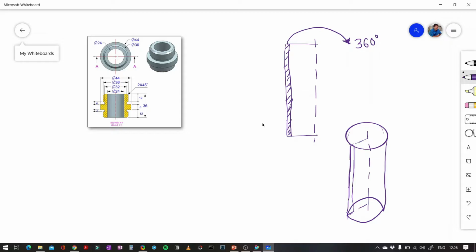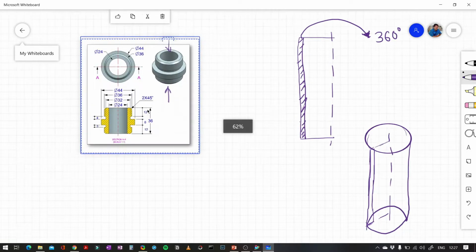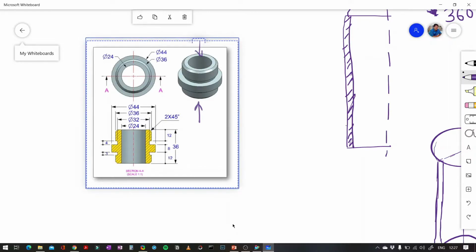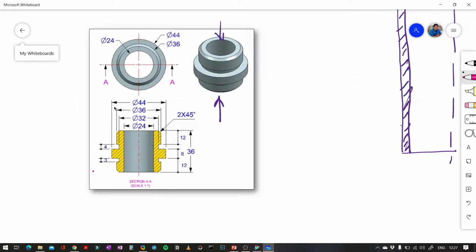Why is this used? We can use the extrusion option here as well, starting from the top or the bottom, and build this model, but it becomes very easy when building these kinds of cross sections using the Revolve command. We just have to build this particular cross section, and the rest is done within a single command. There is no need to use anything else.